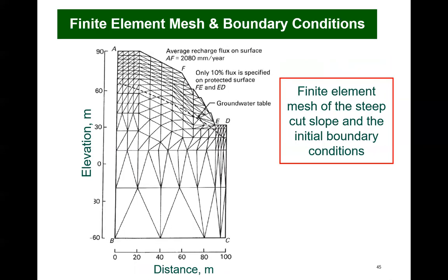It is possible to numerically model changes in the factor of safety of a slope by first modeling seepage from rainfall on the slope. The slope shown here is typical of those encountered in Hong Kong. The water table is at considerable depth, and the zone above the phreatic line is unsaturated. Reasonable seepage boundary conditions were applied to the slope when the analysis was performed.